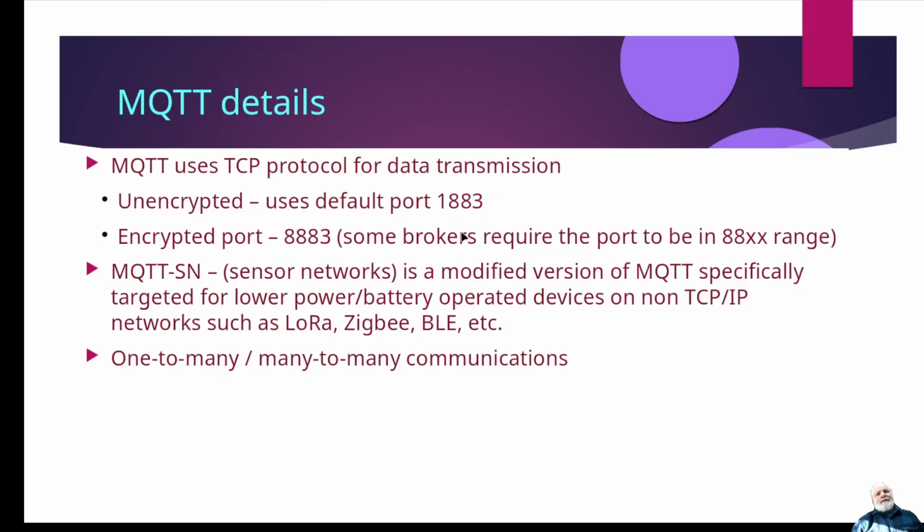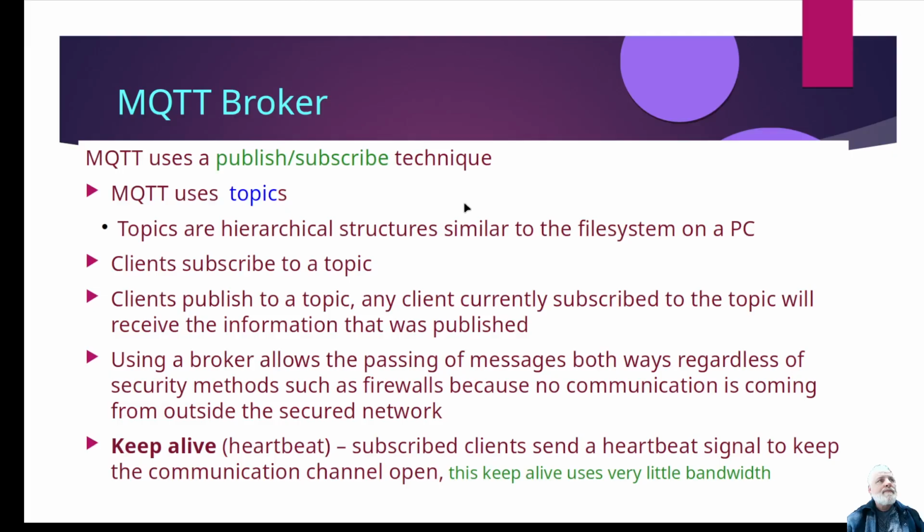The only major thing when you're trying to pick a port is that you don't want to use default ports that are expected to be used by other protocols, and the port should be larger than 1024. All of them below 1024 are kind of reserved for dedicated uses anyhow. So MQTT you can use either unencrypted or encrypted. So again, this kind of gets into using the right tool.